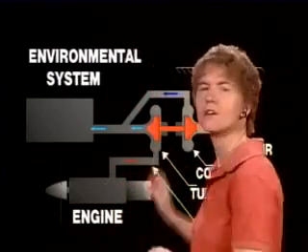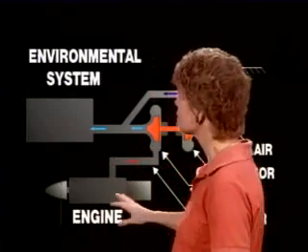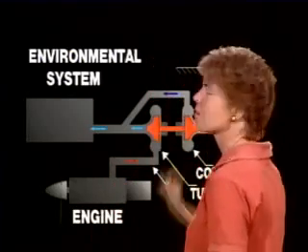One way to stuff a lot of air into the cabin, particularly used in large piston engine aircraft that are going to be pressurized, and also in some of the earlier jets that didn't have all that much engine power, is an independent cabin air compressor. Now, an independent cabin air compressor may use bleed air from a turbine engine in order to operate the compressor, or it can be gear driven through an accessory drive gearing off of the engine.